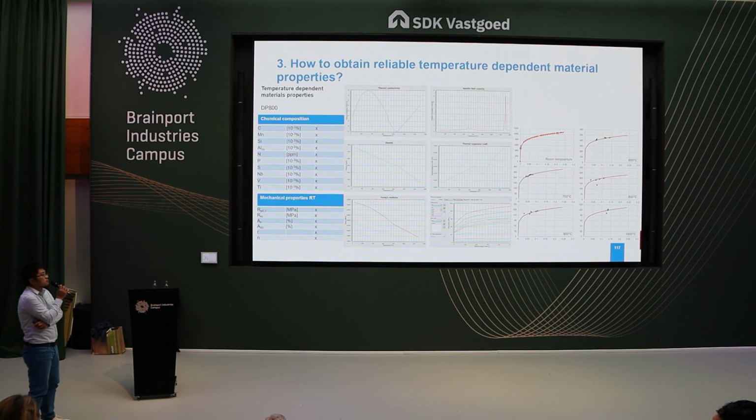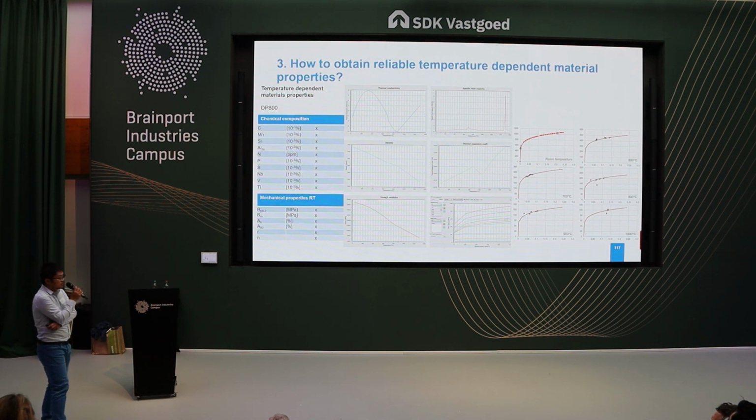But the mechanical properties are not only based on the chemical composition, they are also determined by the subsequent heat treatment or what kind of phases are formed. Therefore, we have to compare with the high temperature tensile test to determine the material constant and also the hardening slope. With that, we can obtain the flow curves at different temperatures. So now we are confident about the material properties.